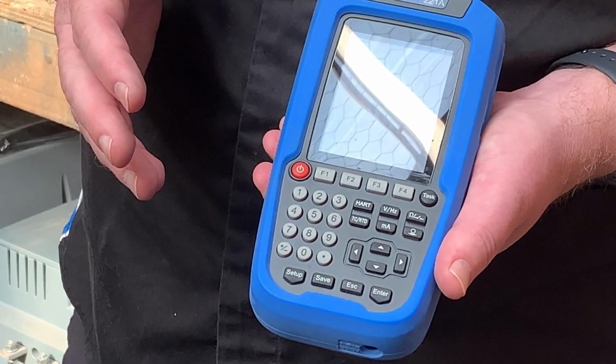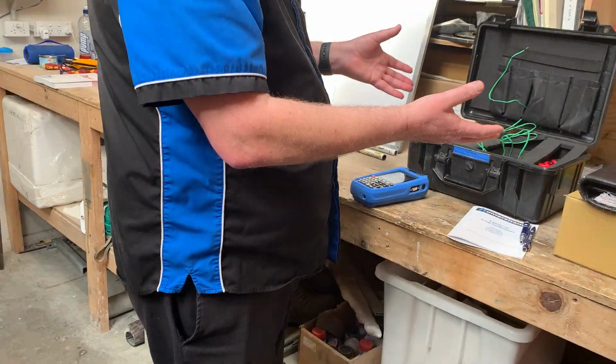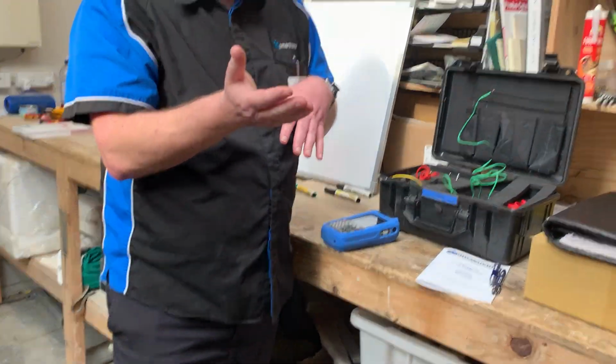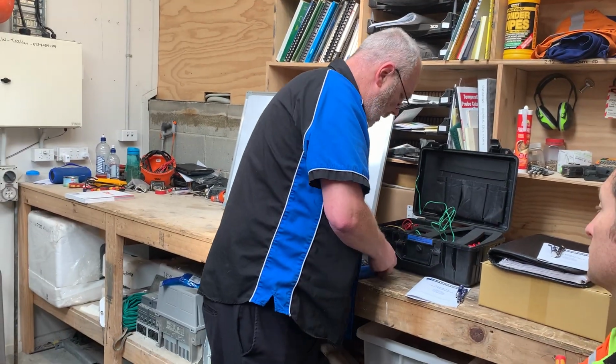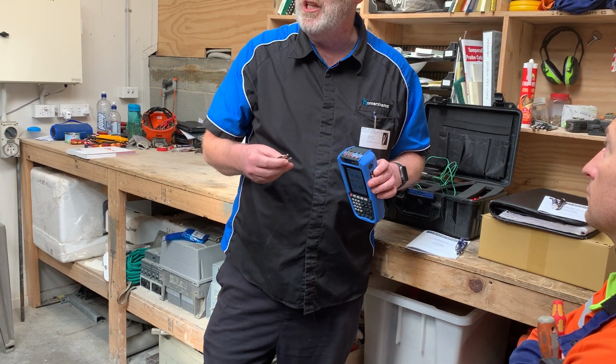How do we use the onboard 24? Okay, that's an extremely good question. So you've got the thing on the bench. This won't have enough current to drive a valve, obviously. It's only going to drive the 4 to 20 milliamp control signal. In the case of using it on the bench, the 24 volt supply is isolated. Those in the know tell me that's a really good thing.